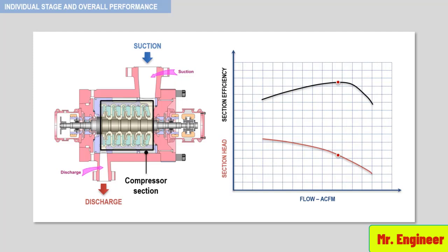Any change in gas density, pressure, molecular weight, temperature or compressibility will affect the flow into the succeeding stage and thus affect the performance. The most effective way to minimize the effect of mismatching is to require that each compressor stage operate as close as possible to its design or best efficiency point.